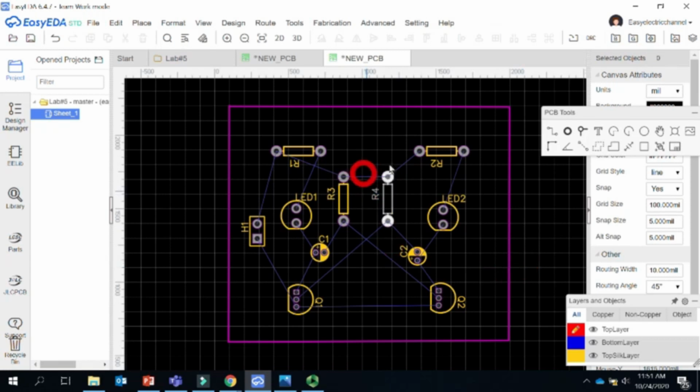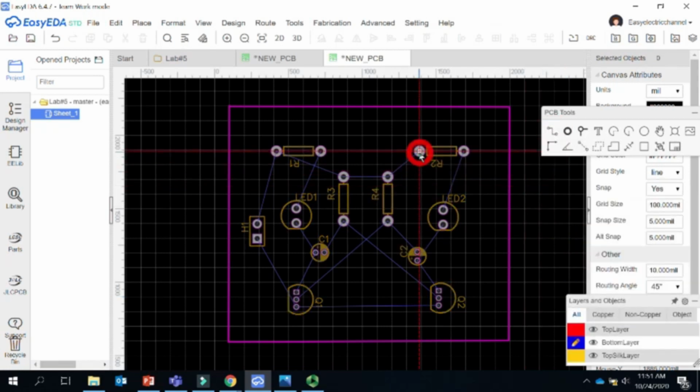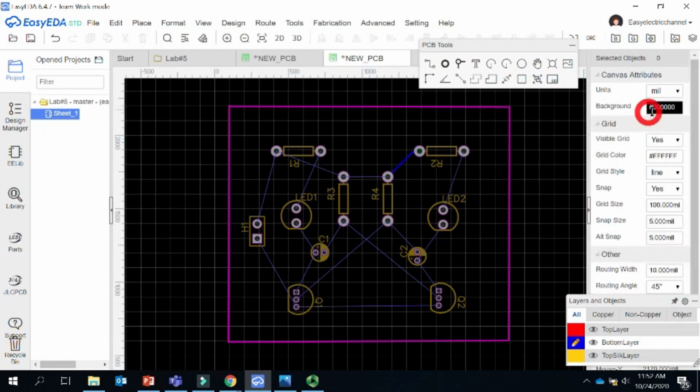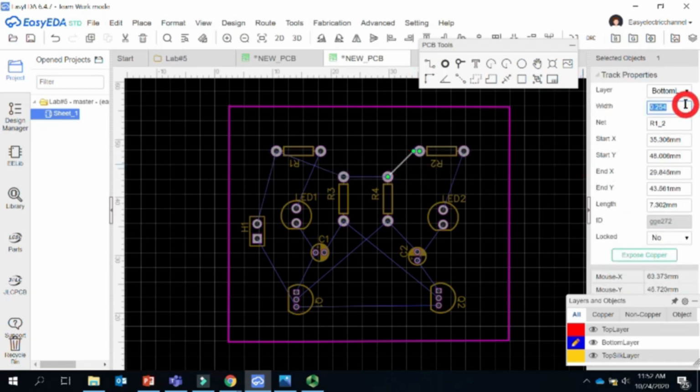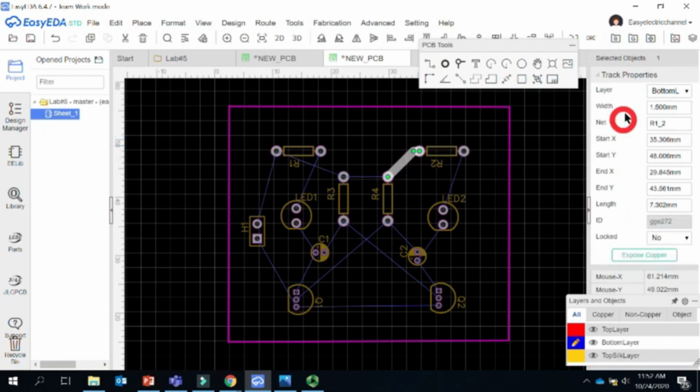So yeah, whenever you are satisfied with your design, then definitely you could come here, go to the bottom line, and here click on the track and make the tracks that you have. So this could be the one track. Other things you need to be careful about: whenever you have a track, click on track and you could adjust your track. Okay, so here let us see, you need to select the units. So you click on the outline here, you select any units that you are comfortable with. I'm comfortable with millimeter, so I click on the millimeter, and every unit changes to millimeter. Then I want to click on the track and adjust the width of the track. So let's put that at 1.5 millimeter, which should be fine, because we should have enough width whenever you are making this PCB board. Okay, let's put 1.5 for the width of these tracks.